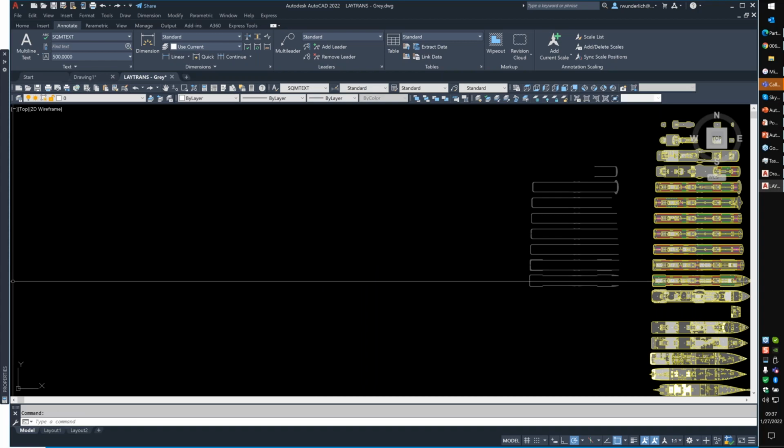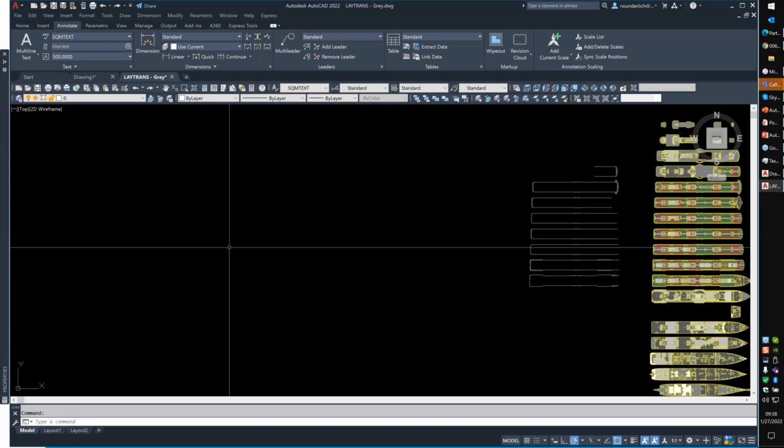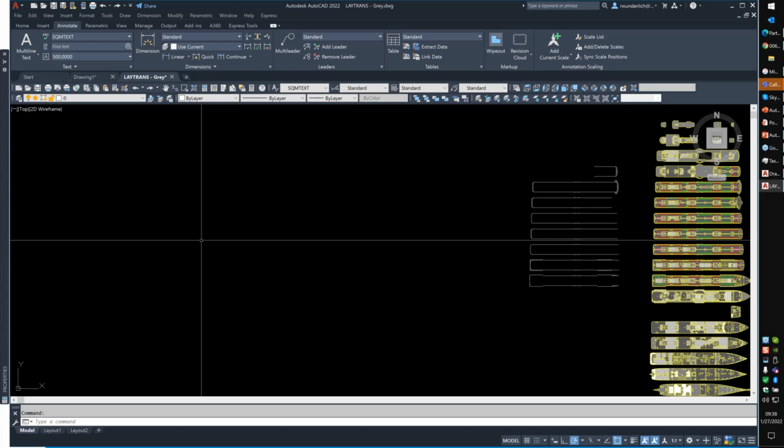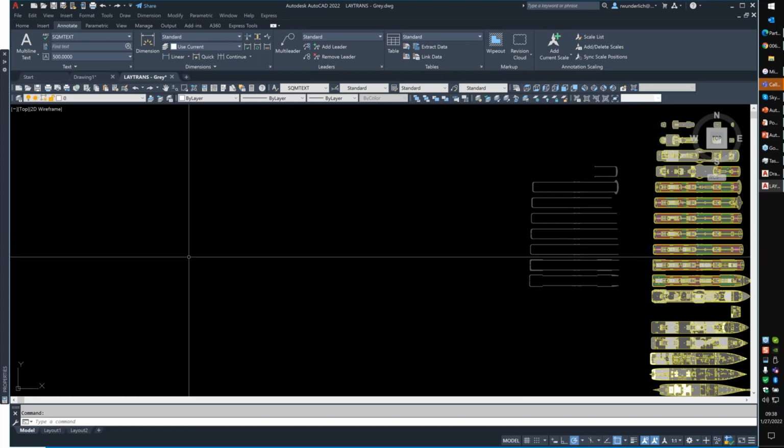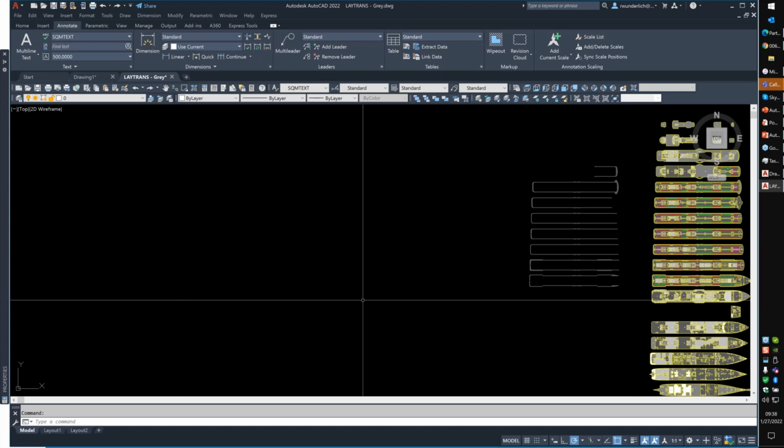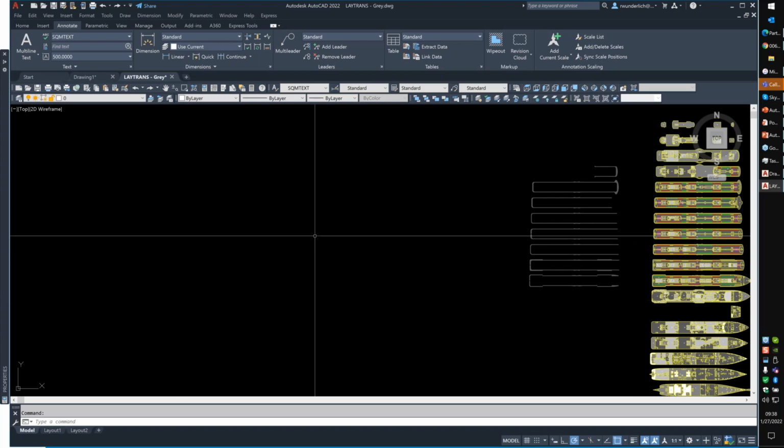Snap angle can be useful on a temporary basis. You are correct. Snap angle just changes the angle of your crosshairs. The only problem I have with it is that if you don't remember to turn it off, it can cause problems for other people who get into your drawings. If they don't understand why the crosshairs are rotated, they freak out.